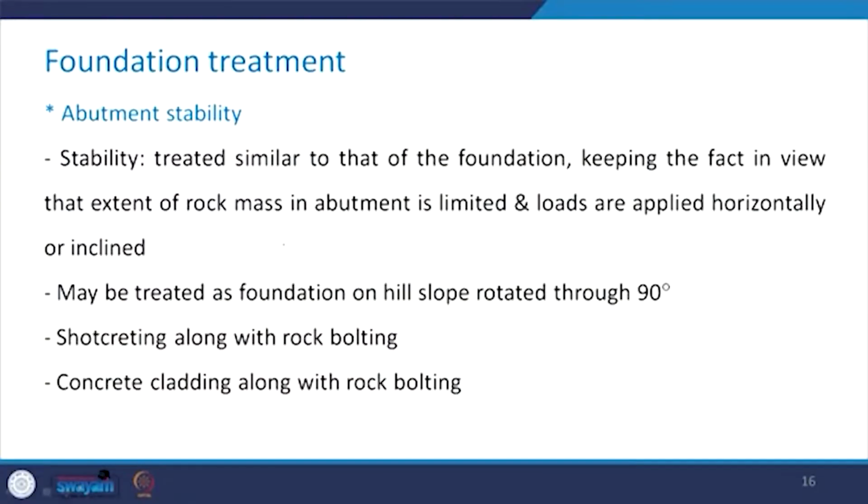It is not only the safety of the foundation that is important, but the abutment stability is equally important. So, the stability of the abutments can be treated as similar to that of the foundation, which we discussed in the previous class, keeping in view that the extent of the rock mass in the abutment is limited and loads are applied either horizontally or inclined.